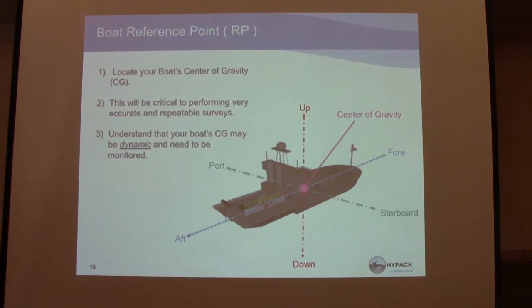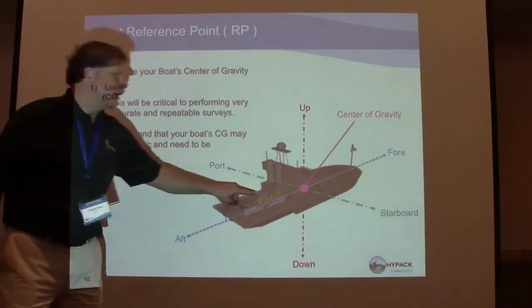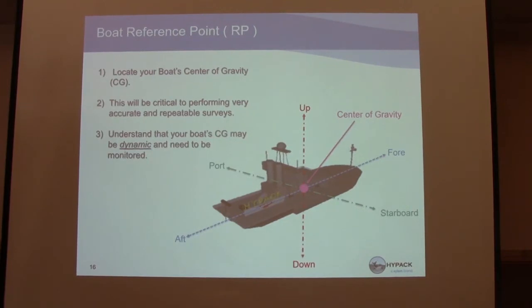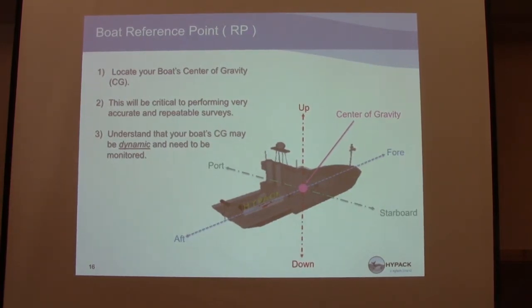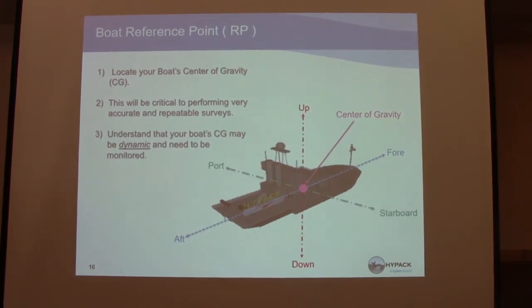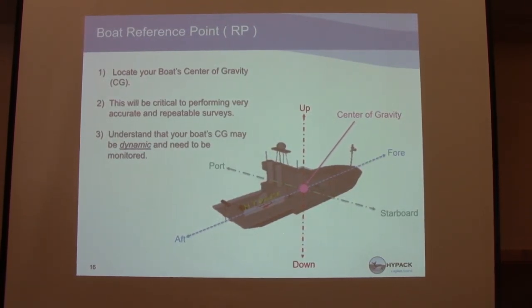Okay? And it's not showing the water line here, but you don't have to be precise with the center of gravity. So if you've got a big boat, you might be able to talk to the naval architect that designed that boat, and he'll give you a pretty good idea of where that COG is. If you're on an Armstrong boat or a Scully boat or Parker or something like that, sometimes you just got to go out there and walk around and go, this is pretty much the center of the boat. Okay? So that the lever arm corrections are computed properly and we get a good position on the sonar on the bottom.